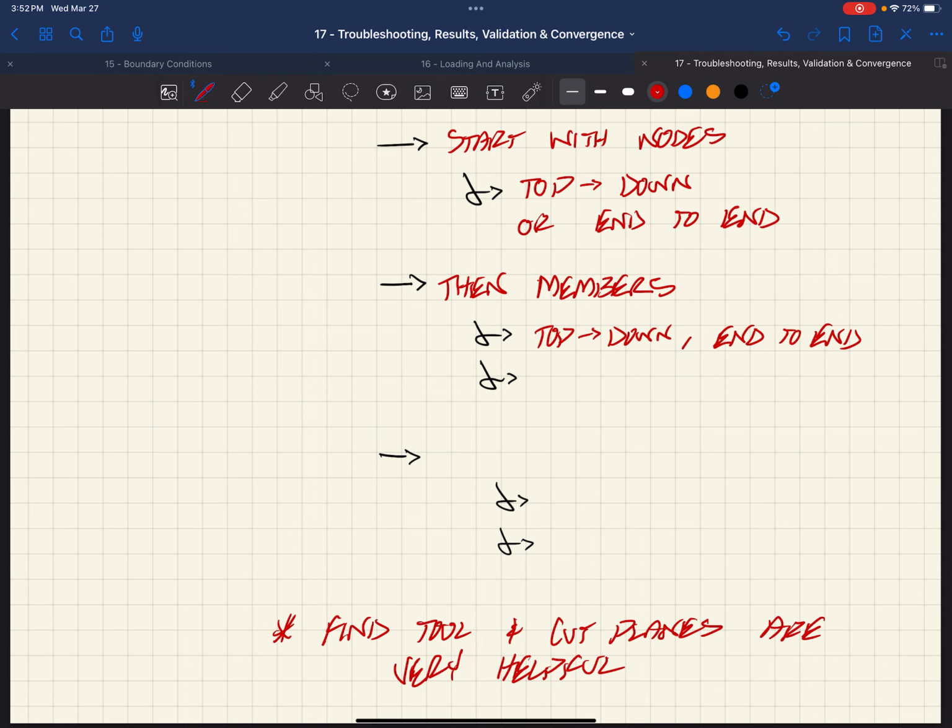So if you had, say, a main wall, and you decide to draw an area on the end of a building, maybe it's the gable end of a residence, right, single-family home, and you put a wind load pressure on it, and all of a sudden you've got bracing in that wall. It doesn't load the bracing with the lateral pressure. It just loads beams and columns, right? Which makes sense that it would.